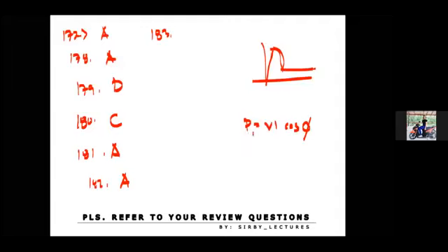So you have the 5 HP, and you have to convert that to watts, of course. This is in volts. This is in amperes, and you have this cosine theta, which is equal to 0.98. So you can solve for this current. The answer here is letter C.